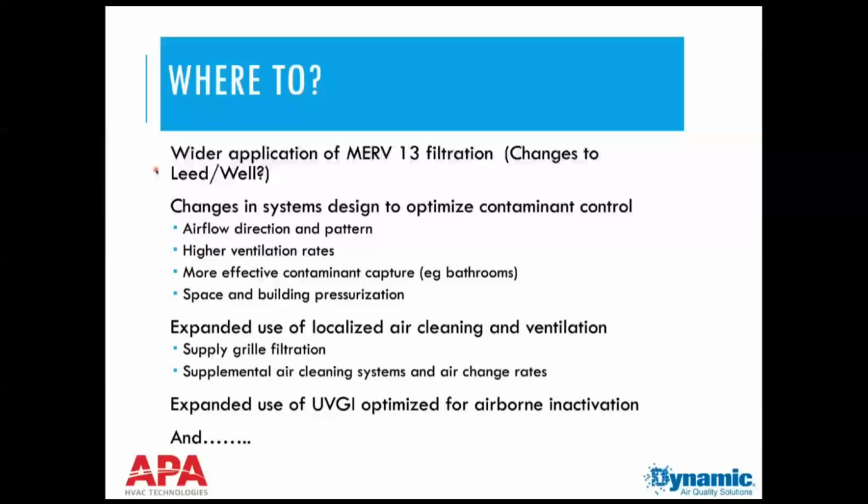And again, I know, because I know what we're being asked to do, that there will be expanded use of UVGI, and not just on coils, but more optimized for infection control, whether that's units, the upper room UV, which you've seen, that's been around for a while, to capture stuff in a space, or whether it's a more aggressive grid in an air handler.